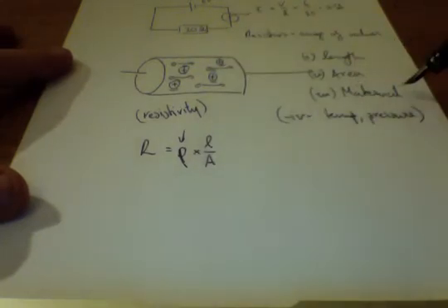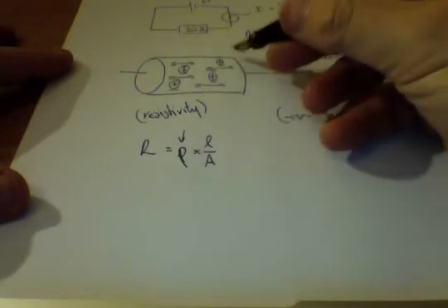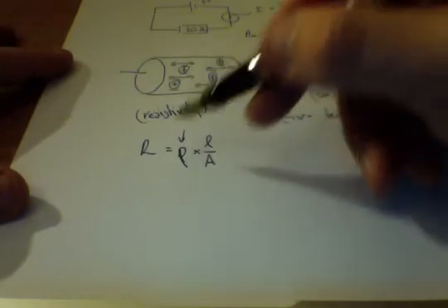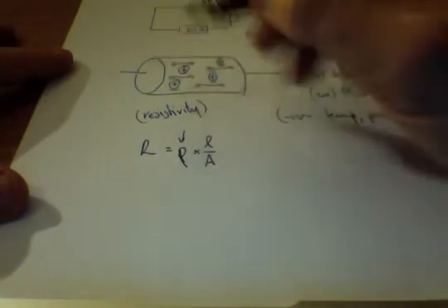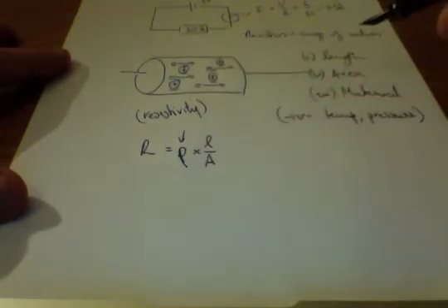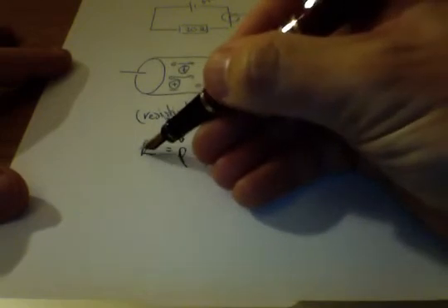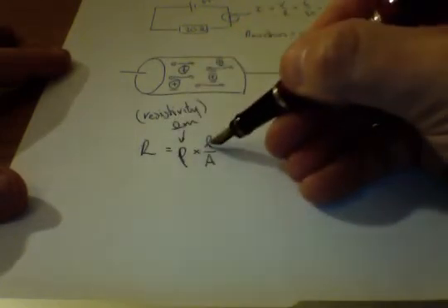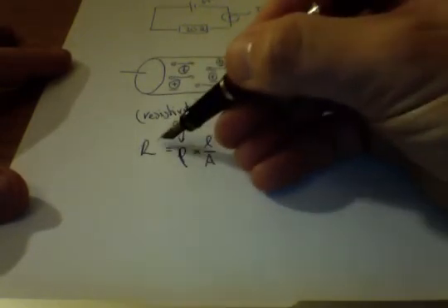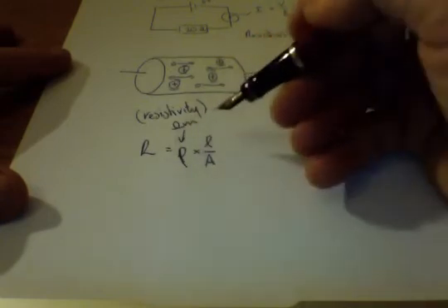It's a material property. So that means it doesn't matter how long the material is or how wide the material is, the resistivity dictates how much resistance a certain material will present. And it's measured in ohm meters. I hope you can see that: ohms on this side, meters on the top, meters squared at the bottom means that meters come up and we can get ohm meters, saying how many ohms does 1 meter of it present?